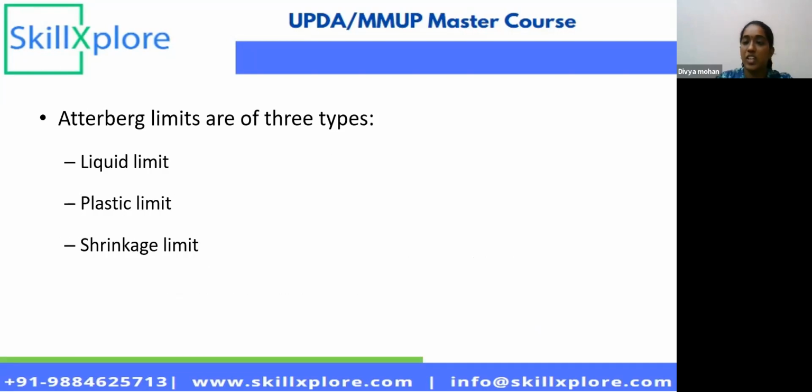And Atterberg's limits, we know that there are three types of limits: liquid limit, plastic limit, and shrinkage limit. Liquid limit is where the soil will behave like a liquid and try to flow when a particular amount of water is added to it. And plastic limit is when the water content in the soil is such that the soil can be deformed to any shape, and it will not behave like a rigid soil.